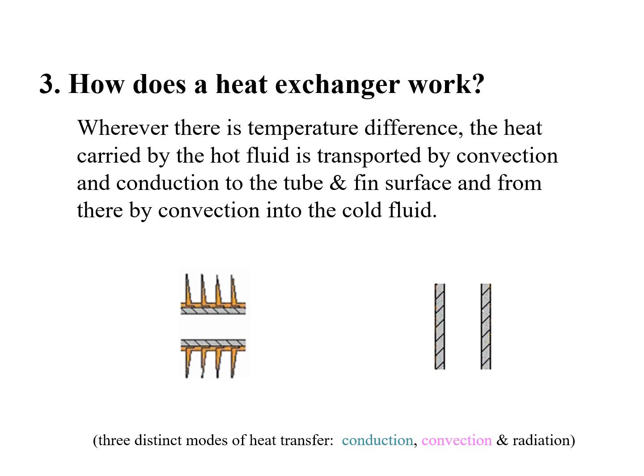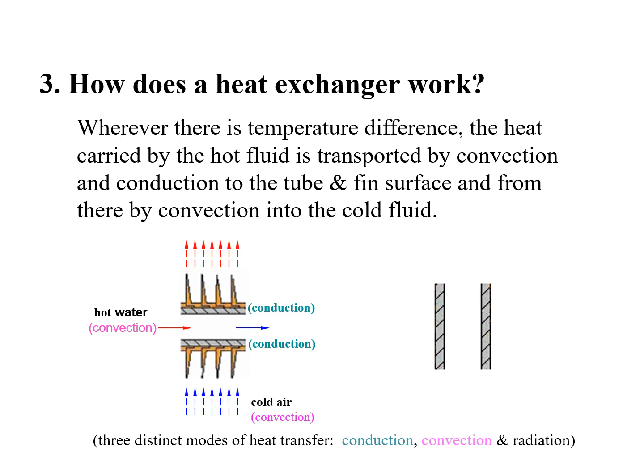In a fin tube, the heat carried by hot water is transferred by convection and conduction to the tube and fin surface, and from there by convection into the cold air. Similarly, in a bare tube, the heat carried by flue gas is transferred by convection and conduction to the tube surface, and from there by convection into the cold air.